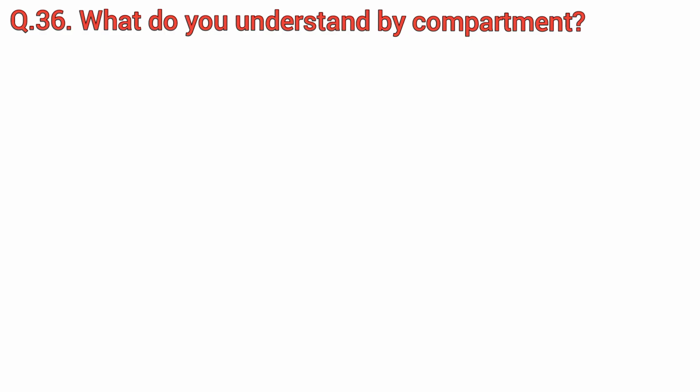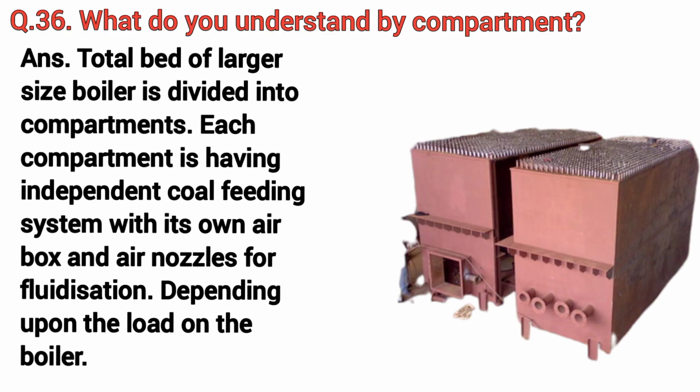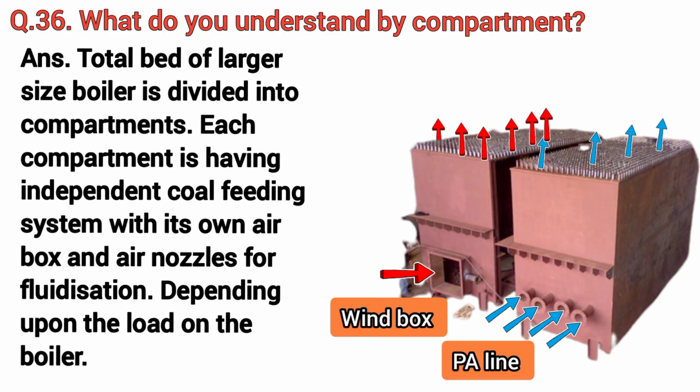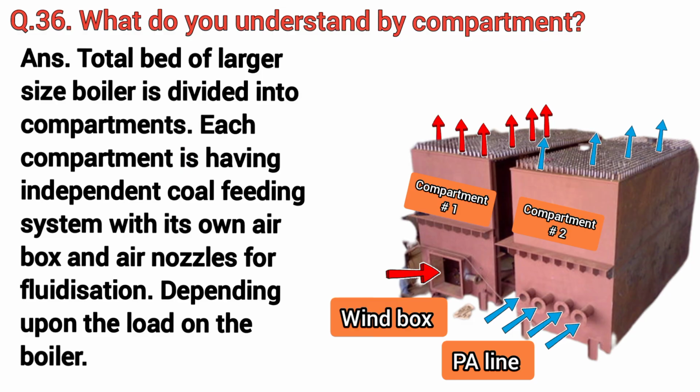What do you understand by compartment? The total bed of a larger size boiler is divided into compartments. Each compartment has an independent coal feeding system with its own air box and air nozzles for fluidization.